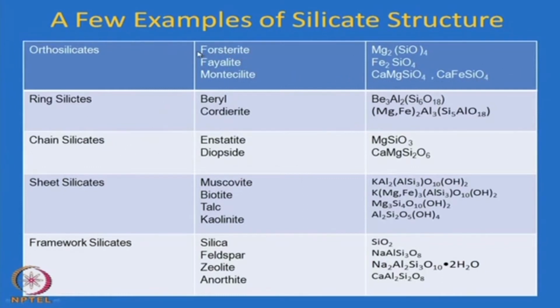In fact, forsterite as such is a very good magnesium silicate, a very good compound which has a very important insulating property, and many of the good insulators do have forsterite, and Mg is added so that this particular phase is formed, and they have a good dielectric property also.